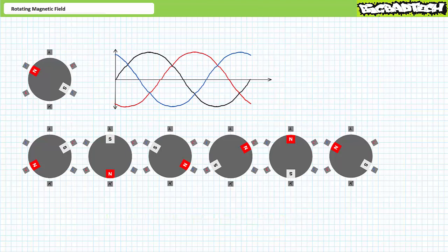Swapping two phase sequences resulted in the complete reversal of the rotating magnetic field. This method is often used in reversing motor starters, a type of bidirectional motor control circuit where a given phase sequence establishes forward operation and a different phase sequence establishes reverse operation. We'll examine reversing motor starters in later lectures in motor control. What's beautiful about this feature is that swapping any two phase sequences results in a complete reversal of the rotating magnetic field, regardless of choice.